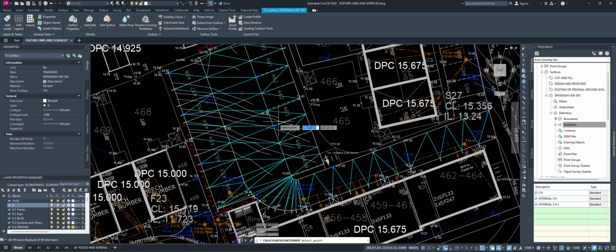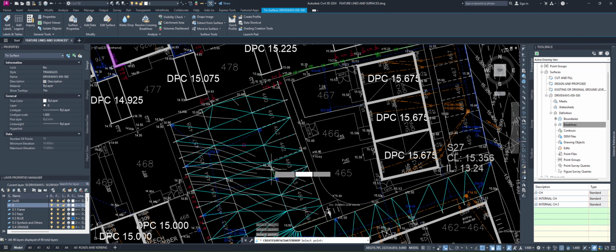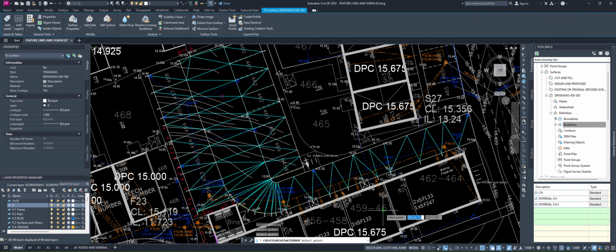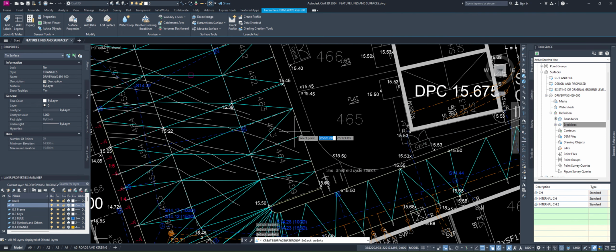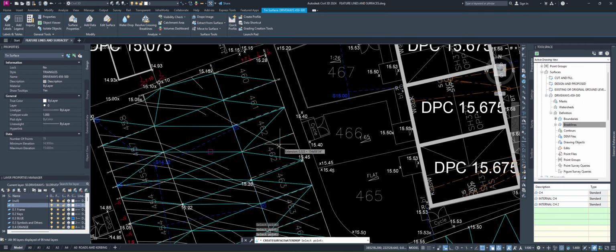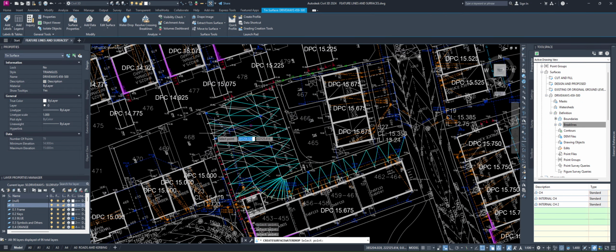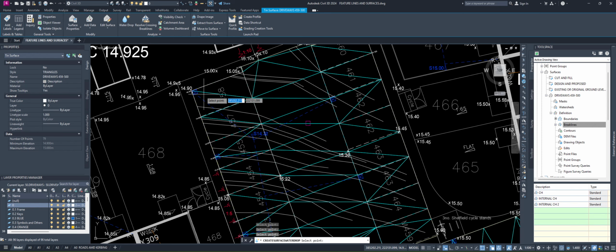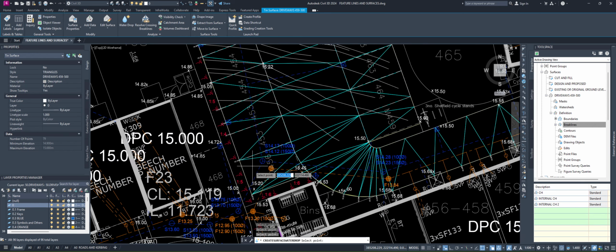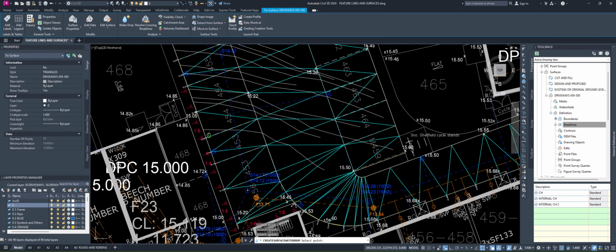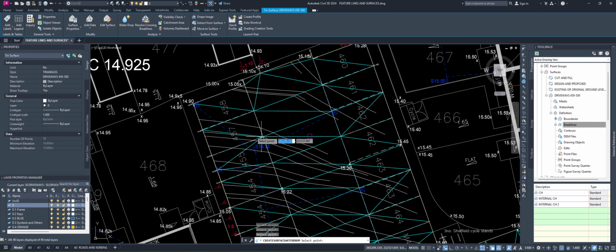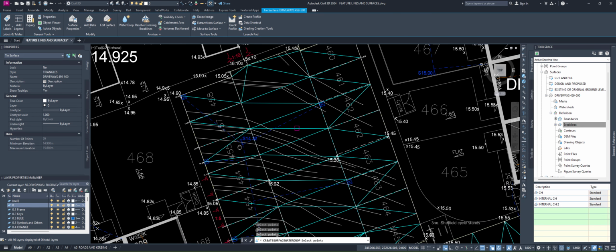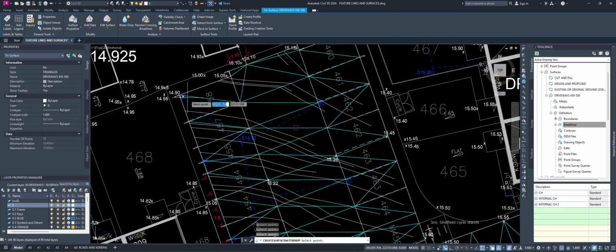Yeah, I think them gullies are just to pick up all the surface water crossing by. Obviously, as you can see, everything is running back this way, so them gullies are going to pick up as much as they can. Personally, I would design this one with a double gully at this end. Everything else is going to run long fall, cross fall and short fall. They both create a cross fall down to that corner.